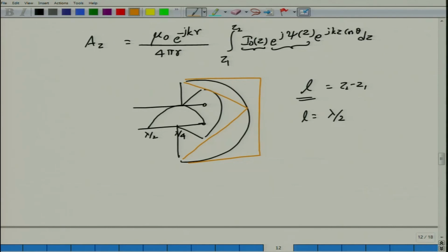In fact, it cannot be like that, because the current is maximum in the middle here, but the voltage will actually be equal to 0. So if you actually connect this one to the power source or the voltage source, it says that there is actually no power transmitted at this particular point because the voltage is 0 and the current is maximum.